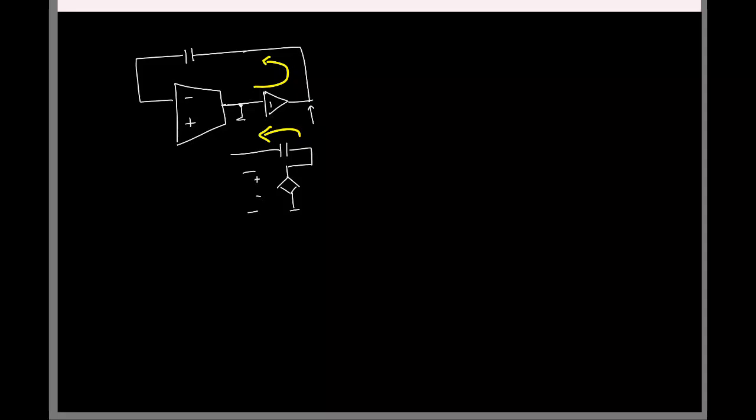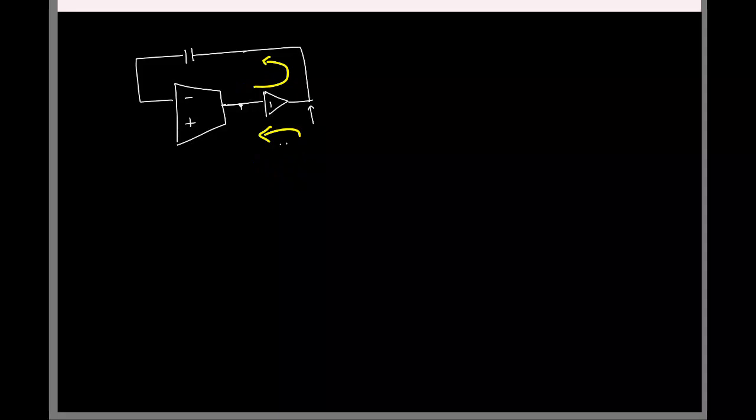I mean, here we have a resistance. The voltage is what is getting buffered. We are finally interested in the voltage. I just inherently assumed that. So the bottom line is this voltage buffer will only allow signal in this direction, from input to the output. It will not allow the signal in the other direction.